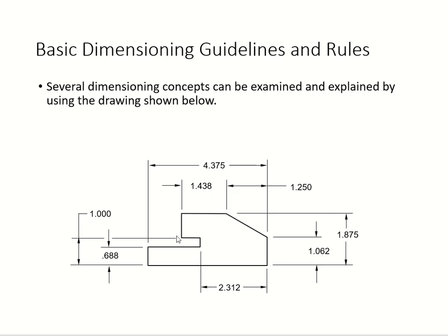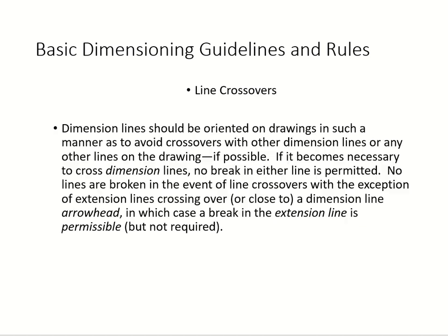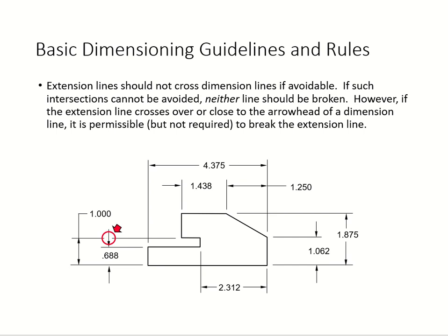Alright, so here you can see the several dimensioning concepts. Value in, arrow in; value out; value in, arrow out, and so on. Line crossover, so let's see how we do line crossover. Look at that, see the line, it's crossover because those two dimensions have very limited space right here, from this edge to this edge, from this edge to this edge.